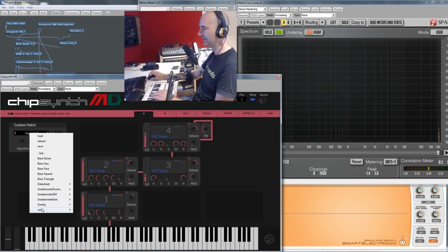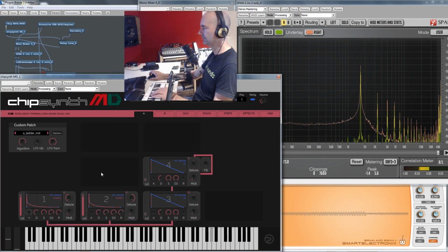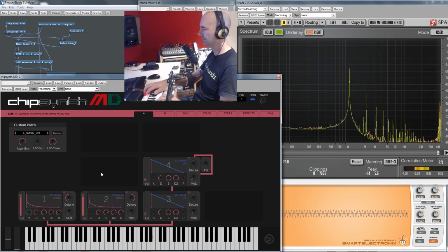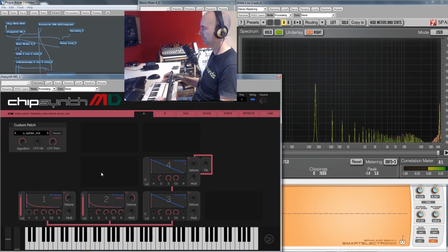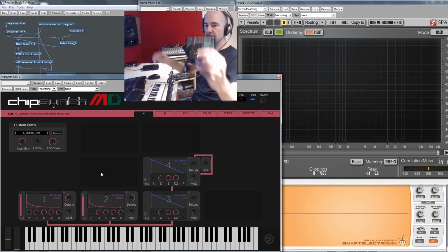Last, before I swap the cartridge, I'm going to do this ladder test here. Wait a second. There's a bit of that because it's a 9-bit DAC, kind of. It is a 9-bit DAC, but it's kind of tweaked in the case of the OPN2C. That was the YM3438.